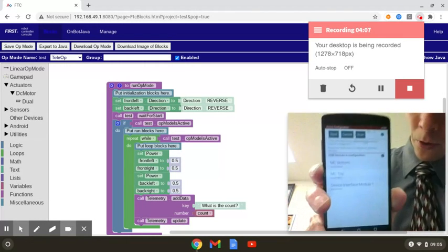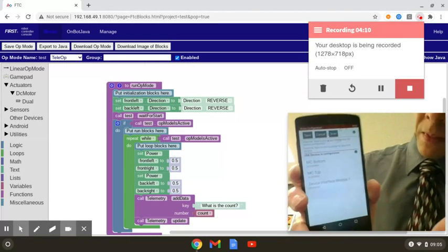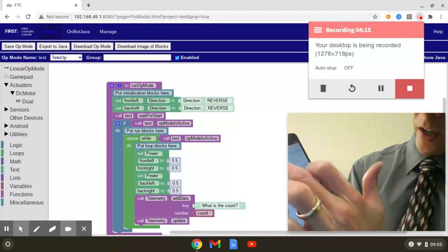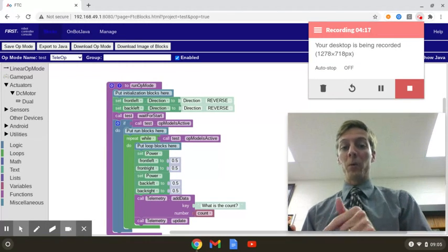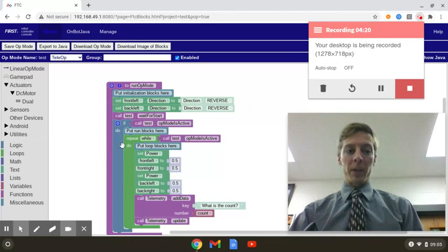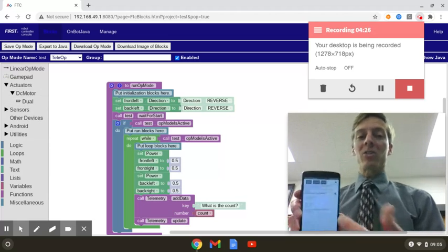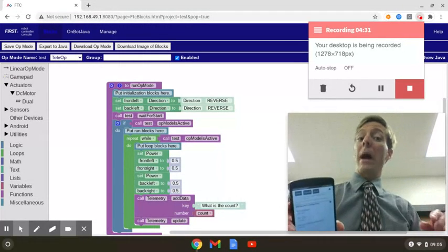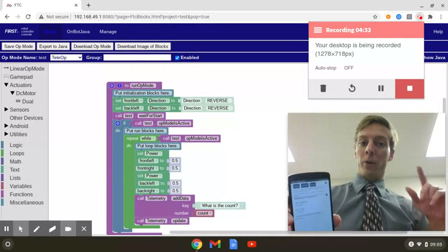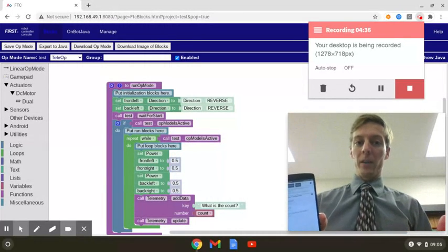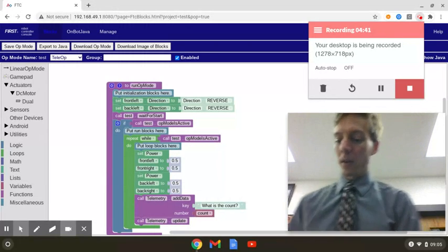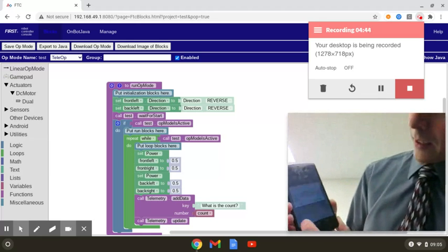This tells you all the things that are plugged into the robot. So here I've got 2 motors plugged in, and then I name the motors. You have to do this on the phone before the motor shows up anywhere over here for you to use. You've got to give it a name. You've got to tell it what type. The types were specified wrong. 2 of the motors were from a different brand, and so they were running backwards. And it caused it to go in a circle and not what we expected. So that's different. But now that that's fixed, let's go back. You save it.